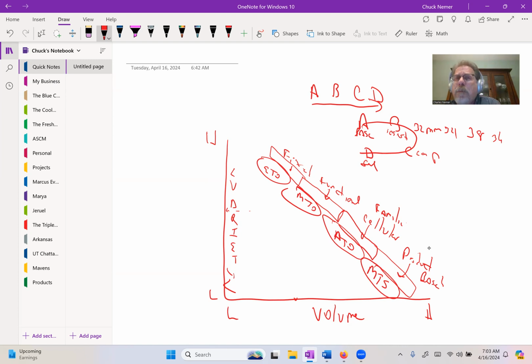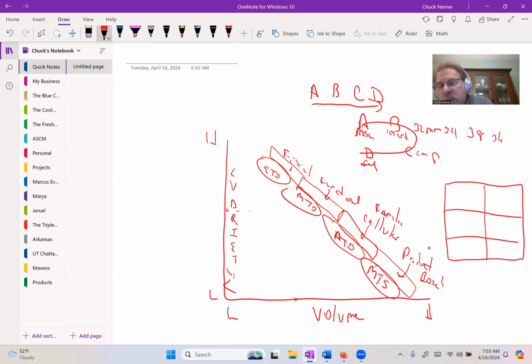Functional, for make to order, typically doesn't have the volumes to set up an assembly line. So we set up the factory in departments, in other words, by the function of the equipment. So if I look at my factory over here, I'm going to break it up into 6 parts. This could be all the shearing of metal, then what's called braking, B-R-A-K-E, where we break the plane of a piece of metal into a 90-degree angle. And then maybe in the third department, we're going to do welding, and then we'll do sanding, and then we'll do assembly, and then shipping. But the volumes are a lot lower, the variety's higher. So we move through departments that share similar function of equipment.